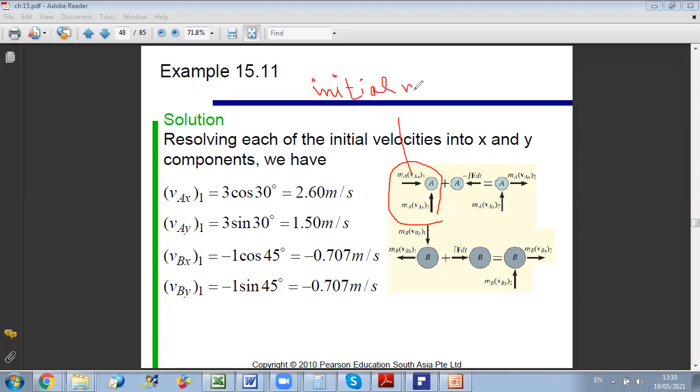Okay. After the momentum diagram we draw the impulse diagram. The impulse diagram will represent the impulse of all forces acting on the particle. Since the contact between A and B, the contact line, is along y, the line of impact will be along x.